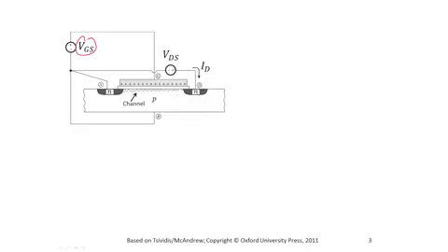Because you have connected the voltage with a plus here and the minus there, the electrons will be flowing towards the plus of the battery, but negative charges going like this are equivalent to positive charges going like that. So if you define a drain current in this direction, then this current will be positive. Of course, if you increase VGS further, you're going to place more positive charges on the gate, which will mean more negative charges in the channel, and therefore the current will increase.